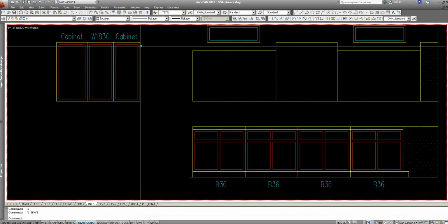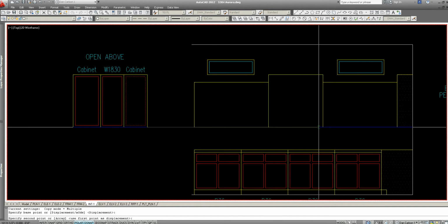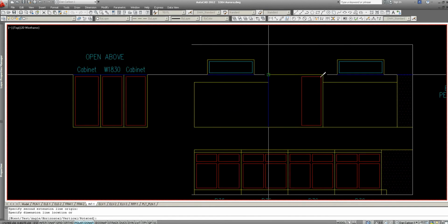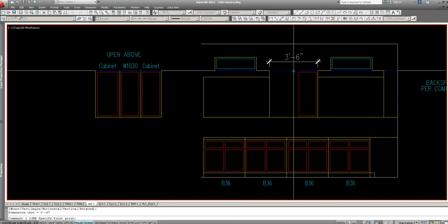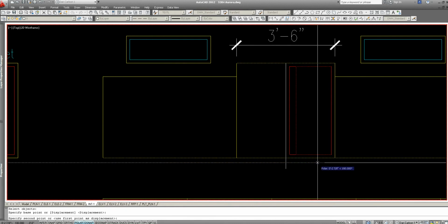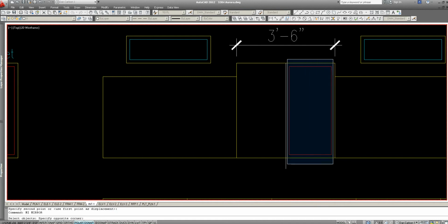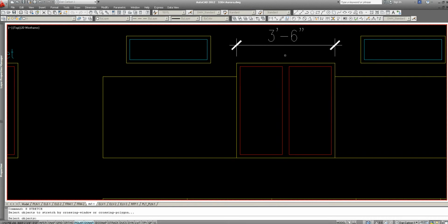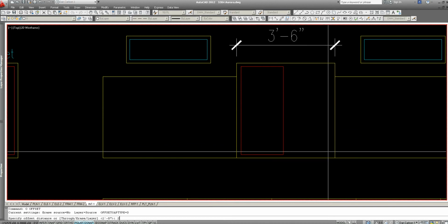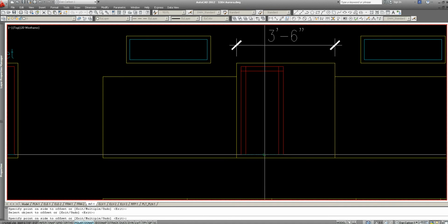So these middle ones, what I was hoping to do is actually do some glass doors, something kind of fancy. And since we know that this is only 42 inches, then we are going to have 2 doors. Anything up to 4 feet will always be just 2 doors. If it goes over 4 feet, then we end up having to do 3 doors. I'm going to just mirror this from the center point. That's pretty good. It doesn't have to be exact. There's no perfection required here. In fact, I'm going to erase this one because what I want to do is create what looks like kind of like a glass door, which just means that you would definitely see the frame.